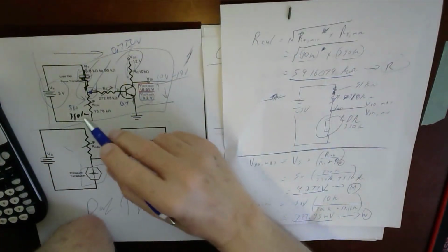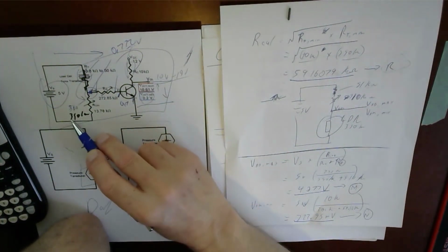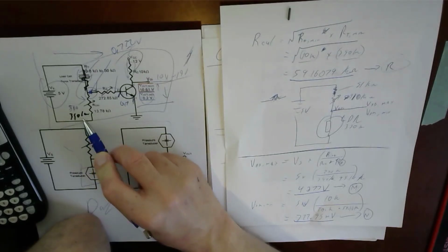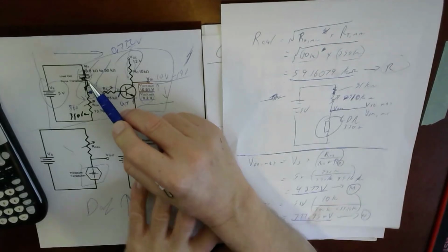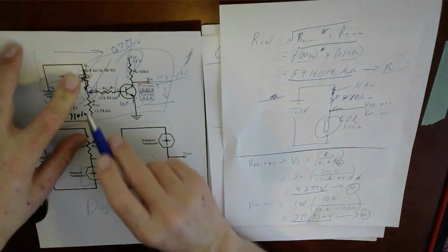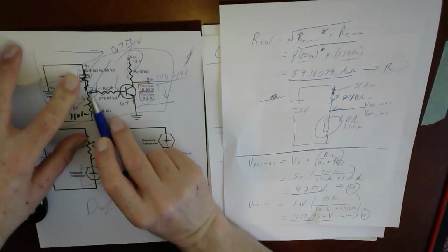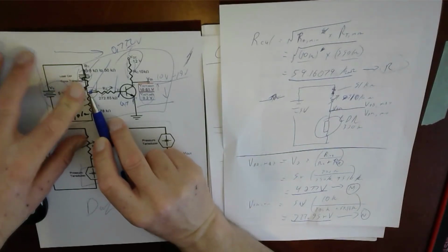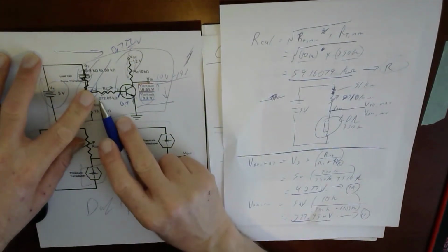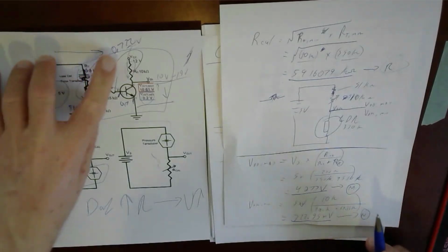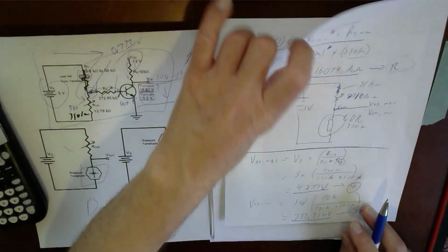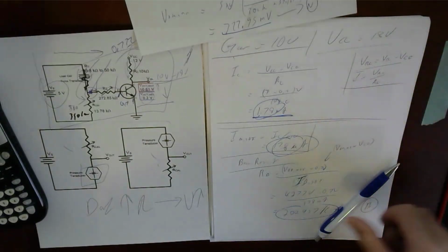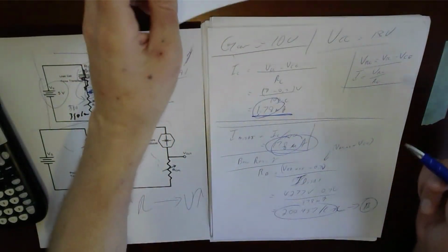I knew that my maximum and minimum values were 350 and 10. So I took this formula here and I found out what my calibration resistor should be so that I have the greatest voltage differential out here. So I did that, not simple. Now, then what I did was I chose 18 volts, and that was from the parameters of the assignment. I want my output to be the greatest, so I chose 18 volts.